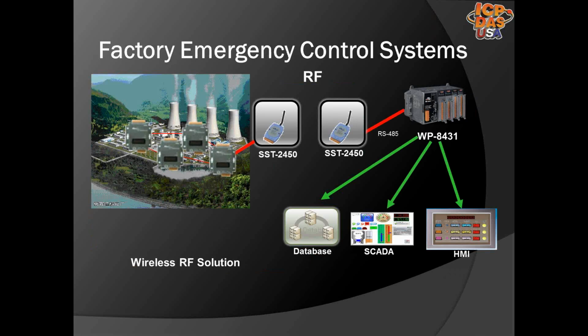In factories, earthquake emergency warning systems shut down machinery and heavy equipment in cases of moderate to large earthquakes. Gas valves are shut off. Access control systems are deactivated. Alarms are sent to emergency responders as needed. Seismic recordings are gathered in a report to determine the amount of seismic energy absorbed by the facility.